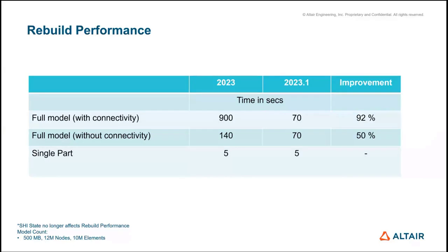I'm not sure if this is mentioned in any of the following slides, but we've also remapped the shortcuts for 23.1. So I believe what used to take you to smooth should now take you to rebuild. And what used to take you to the general 2D mesher will now take you to batch mesher. All this is being done to ensure that your customers will get the best results for what they're trying to do, rather than the legacy workflows that have carried on for many years.